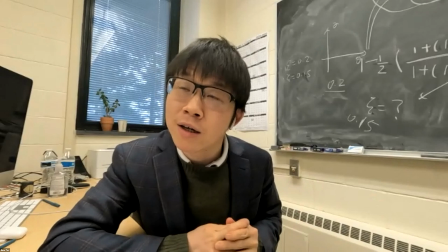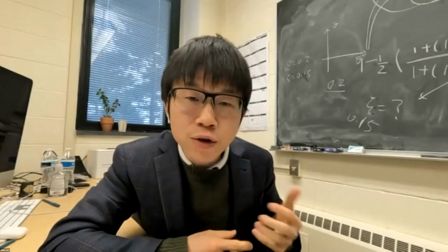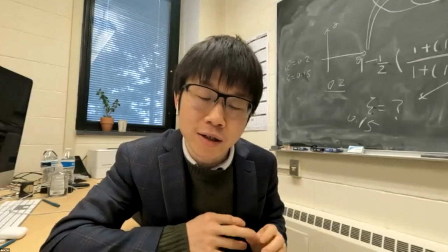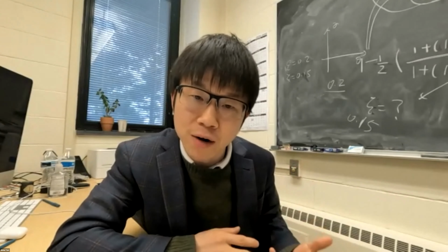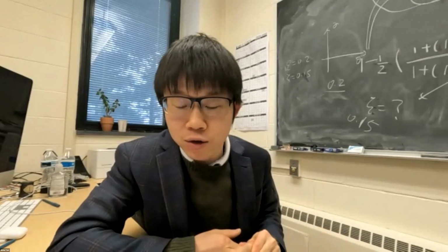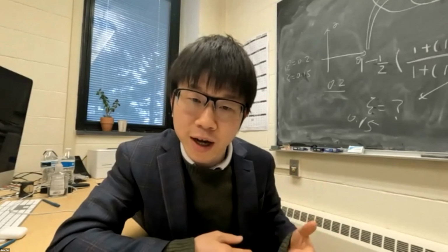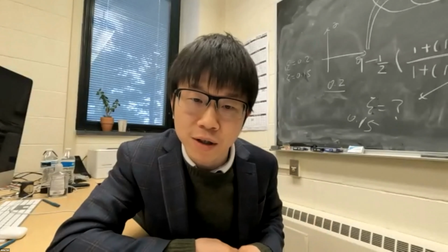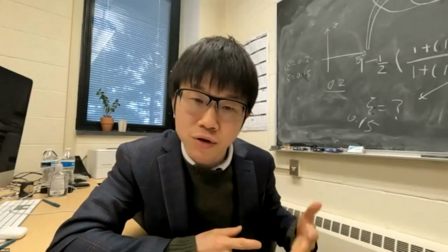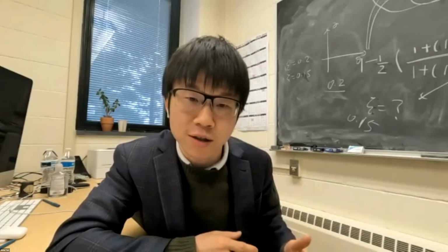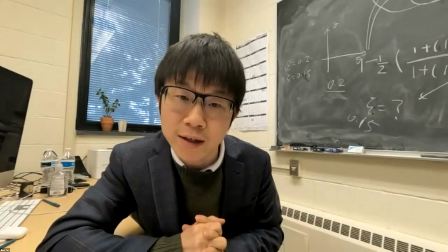I realized that when the Reynolds number is very high, for VMS you can capture the pressure very well, but for the friction stress coefficient, even if you use a boundary fitted mesh, if your mesh resolution is not very high, we still have a very significant discrepancy in that prediction. I wonder whether you have any thoughts on improving the accuracy to predict this type of quantity. I know for other quantities, the results are already excellent.